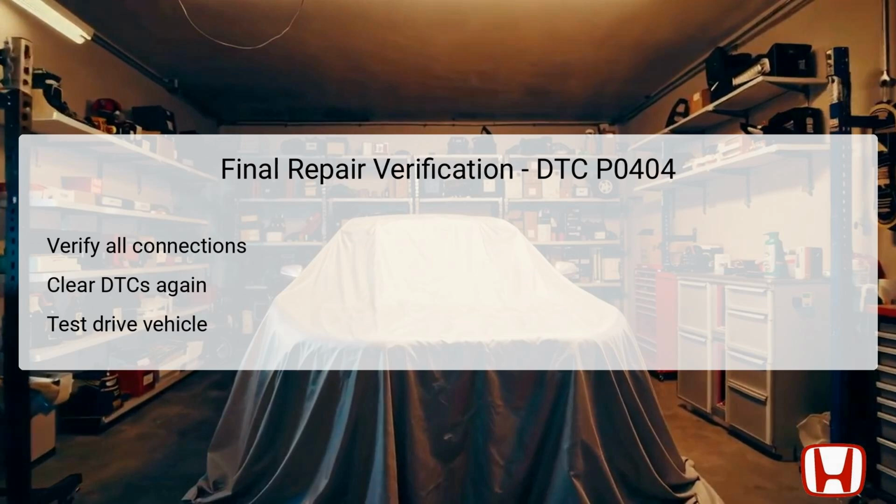Once cleared, take the vehicle on a test drive to simulate typical operating conditions. Monitor for any recurrence of the check engine light or related symptoms that originally prompted the diagnosis. Engaging in this verification step ensures the repair has put the system back into a reliable state, thus confirming the effort put into troubleshooting was effective.